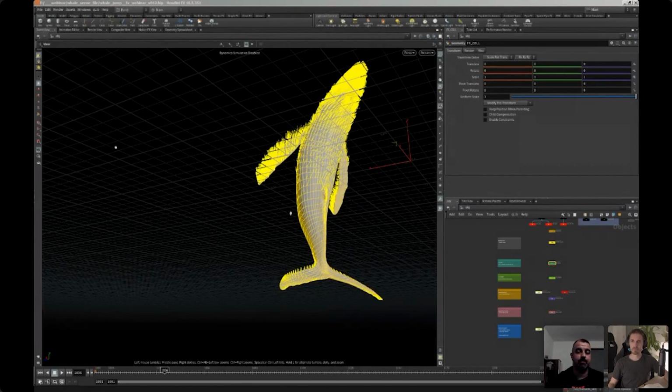crazy high-res shots. I mean, for massive shots, you do the mid-res fluid sim, and then you split, let's say, the splash into chunks and do white water. So let's say you are limited to 20 million per sim because that's the amount your machine can handle. Okay, you do 20 simulations with 20 million. So at the end, when you render, you convert the volume to be more optimized and whatnot, you still can have the massive. But yeah, it's a pain to simulate.